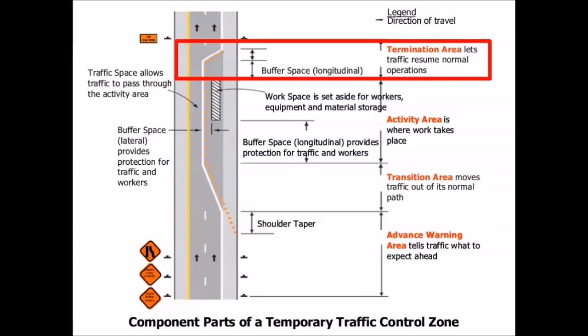And roadwork signs, normally you don't find them for the smaller or shorter operations. You'll find them for the ones that are staying in place longer than 3 days. But again, this is going to be specific for your work areas. Camp Pendleton requires these signs be placed for every traffic control operation.